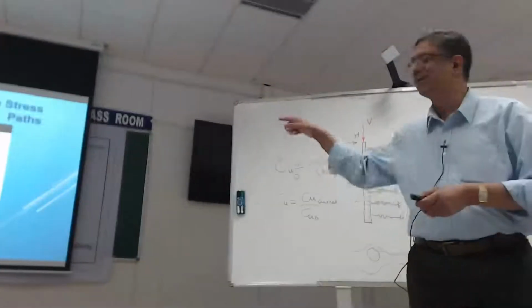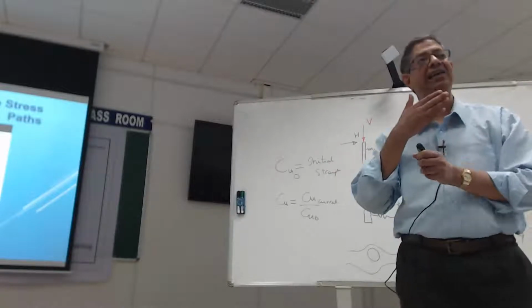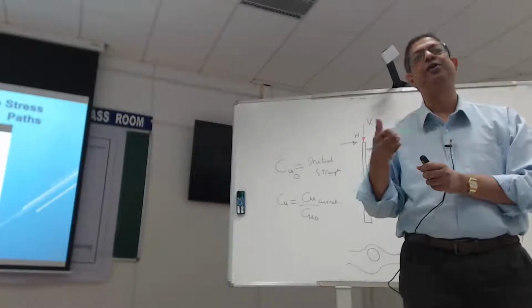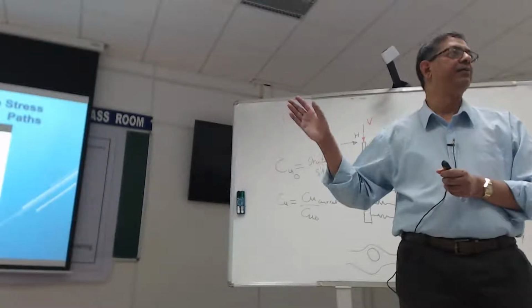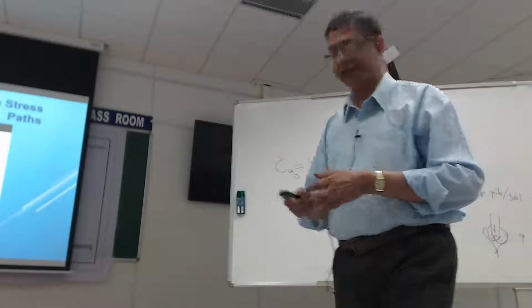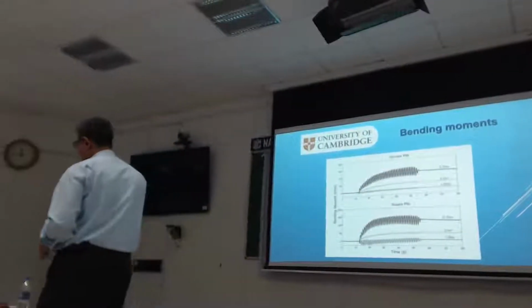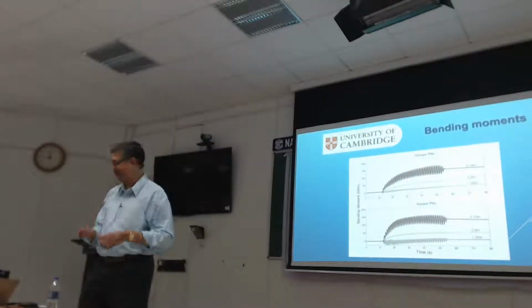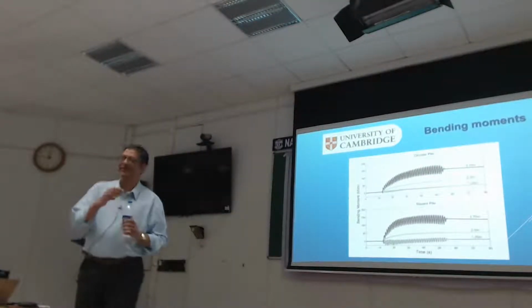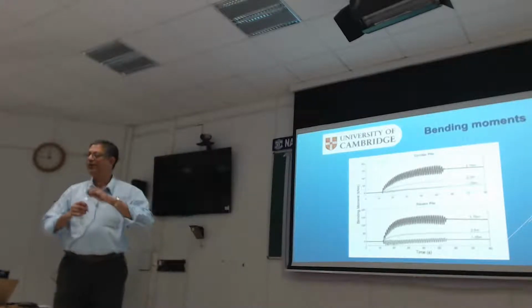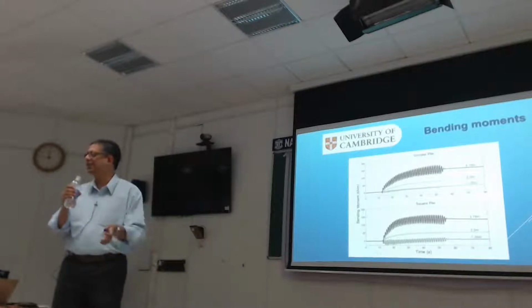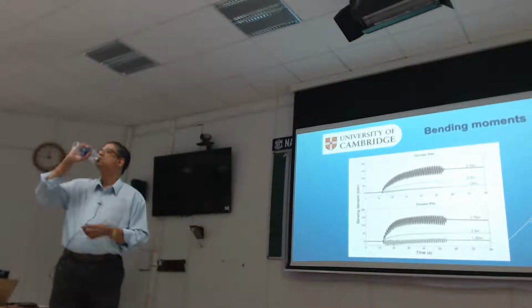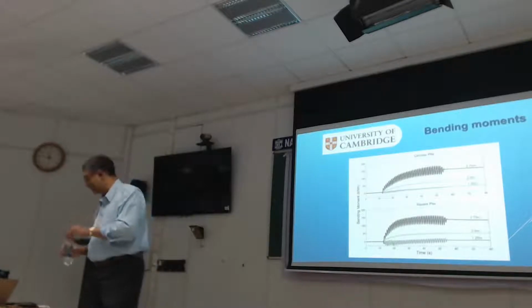This is why, when a pile is rigid and the movements I require of my slope are small, it can oscillate quite wildly between Ka and Kp, which again makes sense. Now, as I said, we tested these shape effects, if you like. Because my original idea for this PhD research was, why can't we streamline piles, to avoid this lateral load from a liquefied soil?